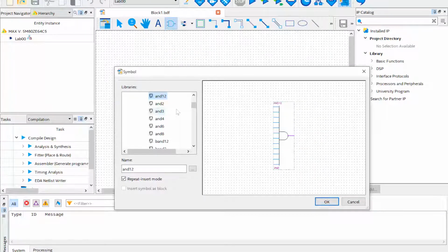In hardware, in the 7400 series chips, I forget what the chip number is, but the largest single gate you can have on a single 7400 series chip is an 8-input gate. I don't think they come any larger. I could be wrong. It happens. But we can actually change this so we can make 12. And in Verilog, it's very unlimited. Obviously you get to a certain point where it gets a little ridiculous. The odds of you using a 12-input AND gate are relatively low, but it's nice to know that you can.